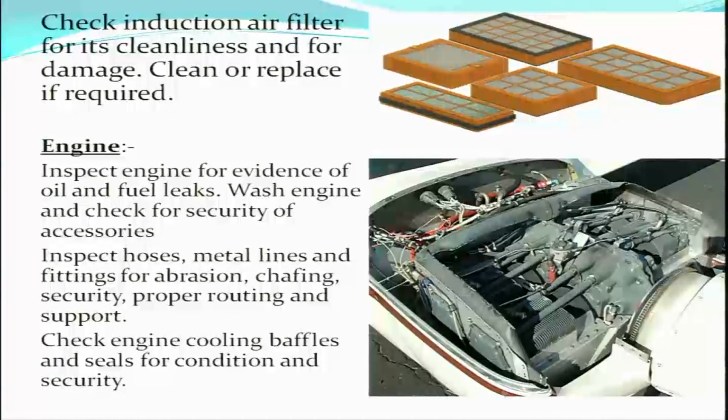Check induction air filters for its cleanliness and for damage, clean or replace if required. The induction air filter is to be inspected for cleanliness and damage, and we need to clean or replace as required. So in the 50 hours inspection, we are also cleaning the induction air filter. We may be required to replace it also. So it is part of the 50 hours inspection.